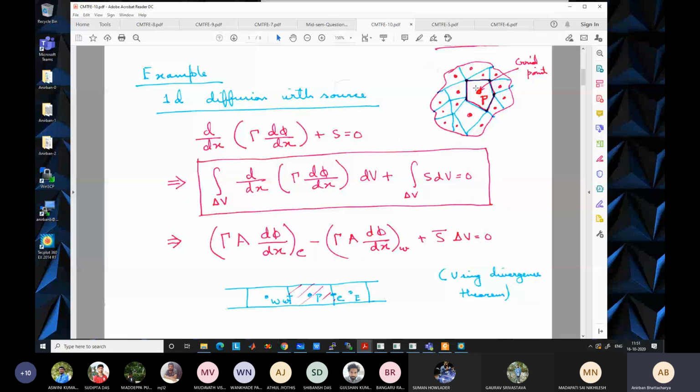But one can also write this as i, and accordingly it will become i+1, j, i-1, j, things like that. But you cannot do this for an unstructured grid. Unstructured means it is very random, so you cannot say how i is increasing in x. There is no x and y for the grids. There the formulation has to be different for this type of problem, which we will see at the end of this course.